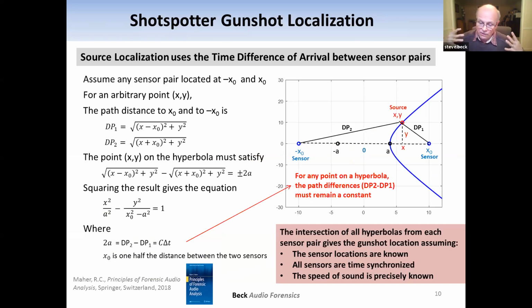So once you get these time differences of arrival, how do you actually locate something? There is a way, if you have these time differences and if you know where all the sensors are, you can compute these hyperbolas. And this is the standard localization technique for these kinds of arrays. These widely distributed, spatial arrays of microphones.